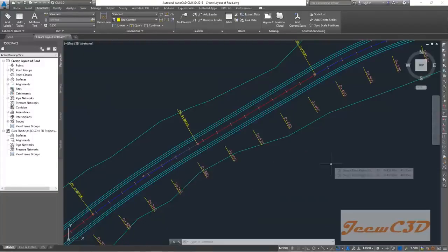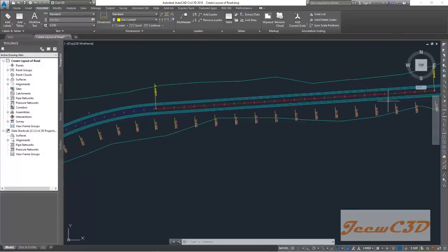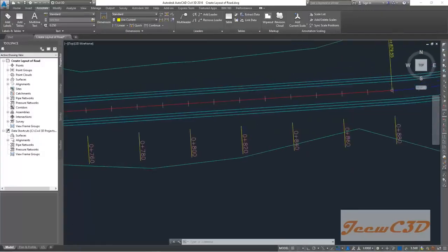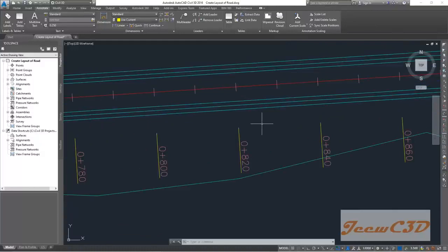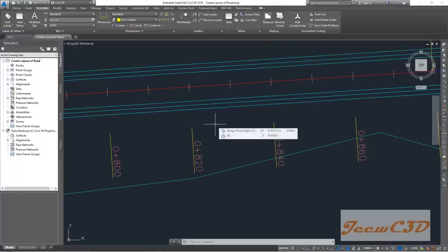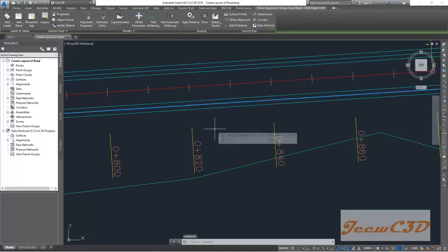Now we are going to find the 820 point in the drawing. This is where we have 820. Then what I am going to do is widen my hard shoulder so that I get the bus bay. So this is how to do it. You click this hard shoulder because the bus bay is at the right side. My chain edges is increasing to this side, so this side is the right side. So I select the hard shoulder of the right side.